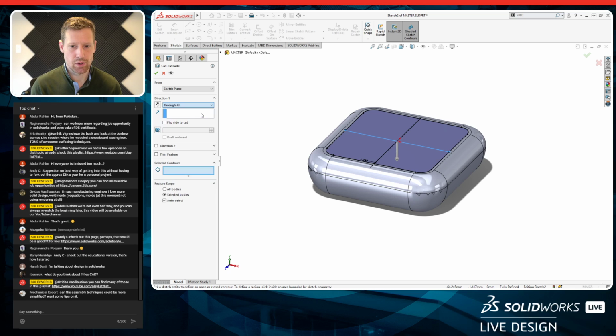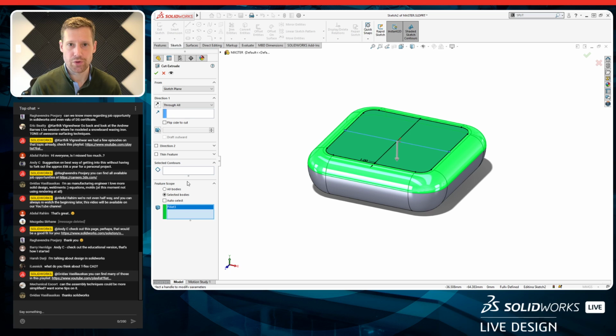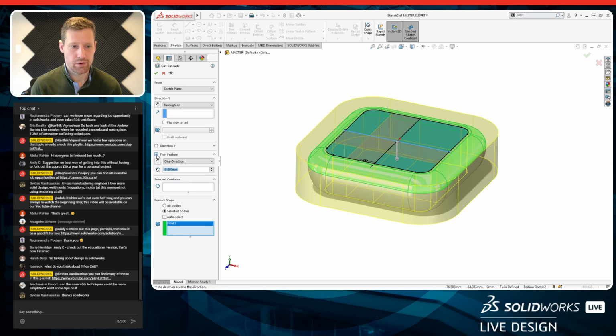Okay, so I want to extrude all this. It's really important that I only extrude through that top body. So even though I said through all, I really only want it to apply to that top body. So that's what that feature scope is going to do down there. That's really useful. So we do have through all, and I'm not getting a preview. And the reason is because SolidWorks doesn't know what I want to extrude. But here's the trick here.